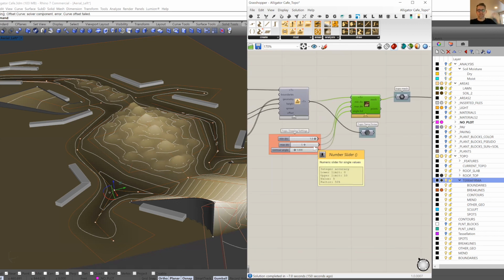And the neat thing about that is you can change the settings for how the topo gets drawn. So you can sort of think of it as a variable resolution topography. You have all these inputs that are always the same, but then at the very end, you can change the rules for how it's drawn, which is kind of great. So if you're dealing with a more complex terrain, you can have a lower quality up until the point where you're ready to have that final mesh for rendering or whatever.